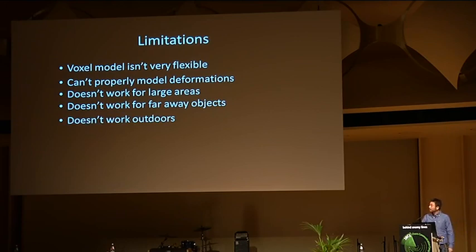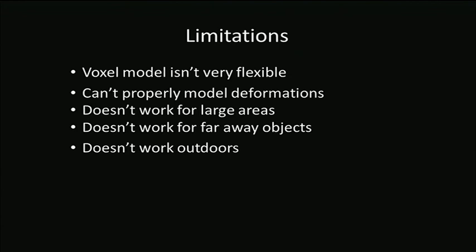Another limiting factor of Kinect is that it doesn't work under sunlight. Kinect operates in the infrared wavelength spectrum, and because the sun also emits infrared, we can't create enough contrast in the sensor image to acquire the depth of surfaces.